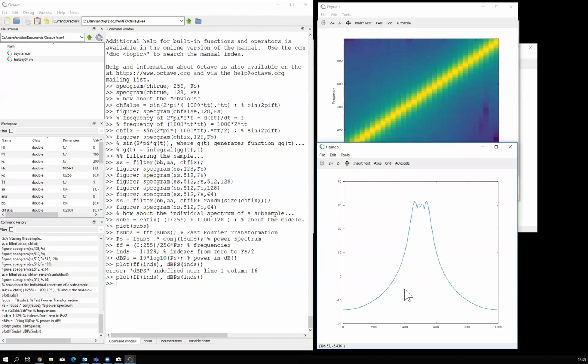This is the power spectrum of my signal, which has no noise on it. So this is a pure signal which doesn't have any noise. So what we see is the envelope of the window. That cape of that Batman is actually that window. And we have chirp frequencies between 450 and 550 hertz. Kind of makes sense. In the middle we should have 500 hertz, but on the other hand we took points on both sides. So this actually makes a lot of sense.